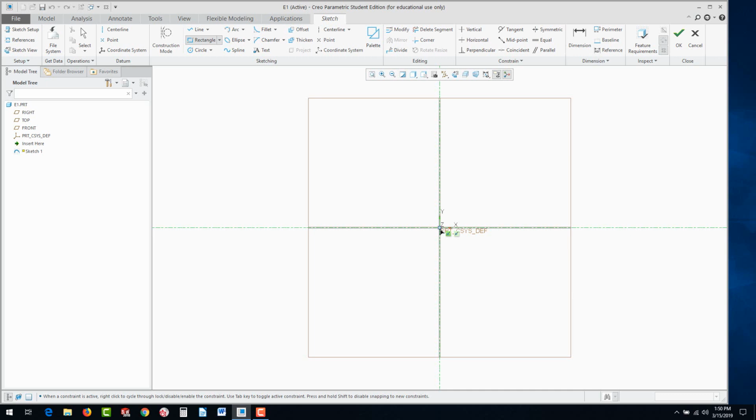There's 2 types of entities that you could add in this parametric modeler. And basically one of them is dimensions, so for lines, circles, and arcs you could dimension them. But you could also add an additional layer essentially of constraints. And constraints are listed up the top there where you see constraints. There's vertical, horizontal, perpendicular, coincident, right up here where I'm looking. And so many of them are automatic as you snap, but some of them you could add in later on. So those are the two types: there's constraints and dimensions.